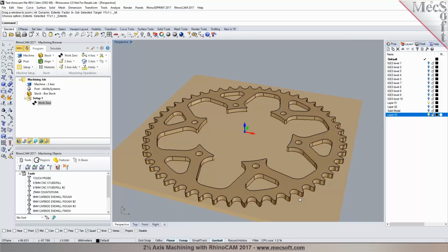Now, how do you typically plan to program this in here? You want to probably do a profile cut around these areas on the outside, and you need to cut these pockets out, right? Yeah, that's correct. And on the inside, do you plan to just do like a profile cut, or do you need to do a pocket too? One profile cut. Okay, so let's start with the inside profile cut in here.